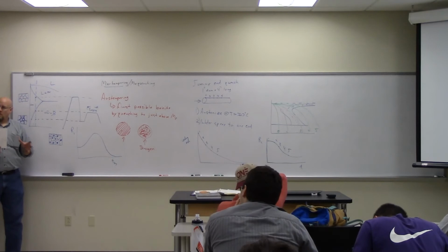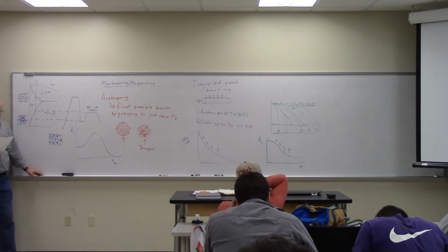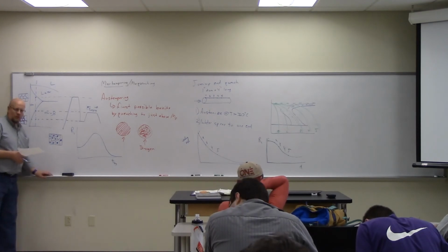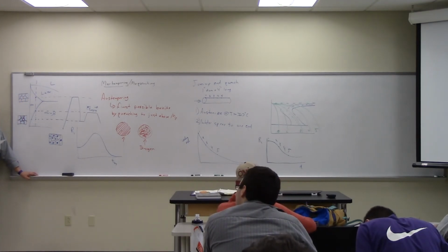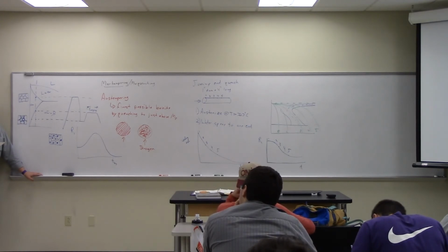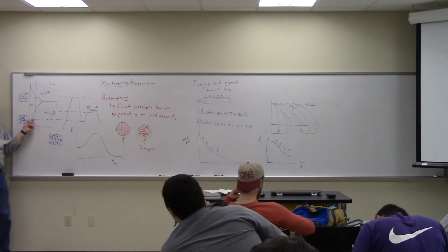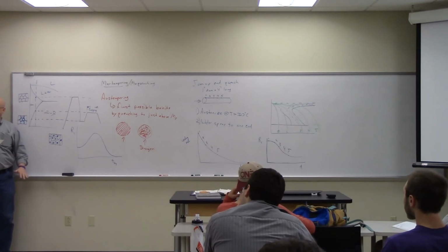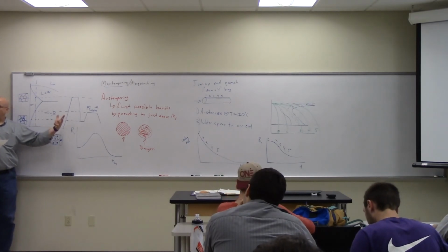Does that make sense? Is it quenching to bring it down, or is it just kind of cooling it? It's not really a rapid quench or anything. I suppose if you did a rapid quench, you might not get full conversion to the equilibrium concentration. If you quench it down far enough, fast enough, then you may not get the actual alpha beta distribution that you're supposed to have, because you inhibit diffusion of the B material to even form more beta.